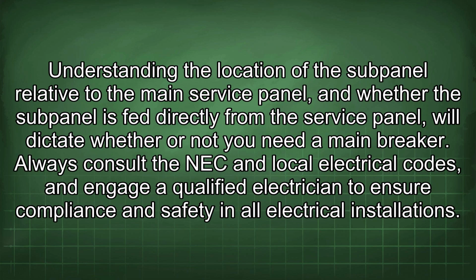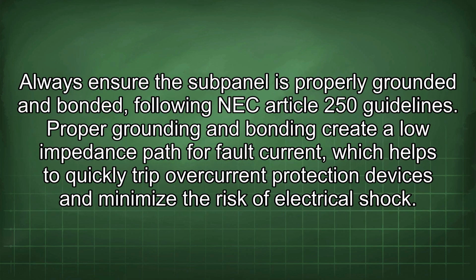Understanding the location of the subpanel relative to the main service panel, and whether the subpanel is fed directly from the service panel, will dictate whether or not you need a main breaker. Always consult the NEC and local electrical codes and engage a qualified electrician to ensure compliance and safety in all electrical installations. Always ensure the subpanel is properly grounded and bonded following NEC Article 250 guidelines.